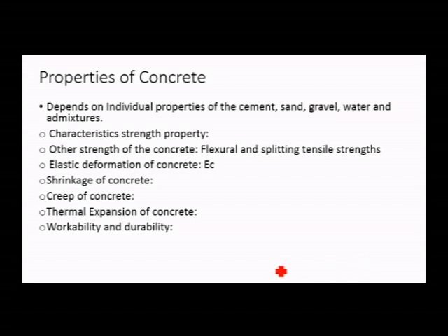Other characteristics of concrete are flexural and splitting tensile strengths, and elastic deformation should also be considered, where Ec is equal to 5000 root fck.